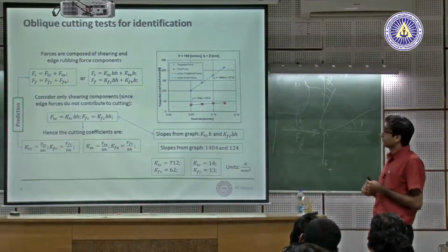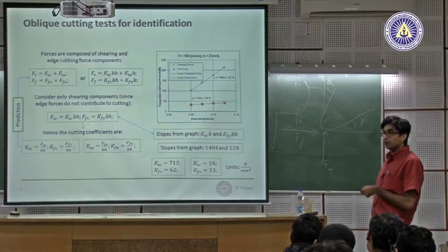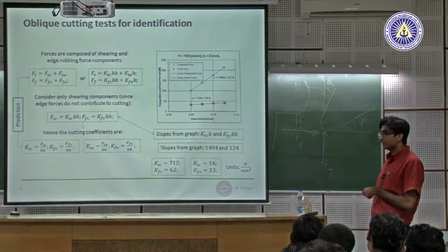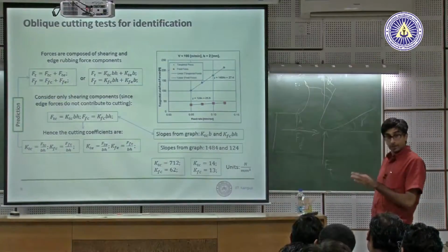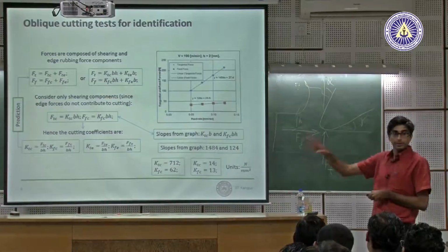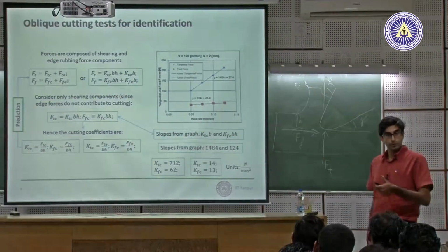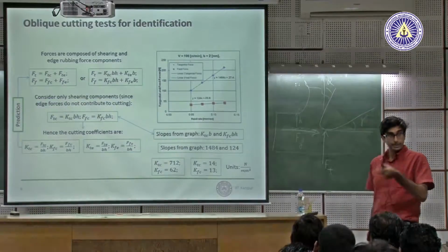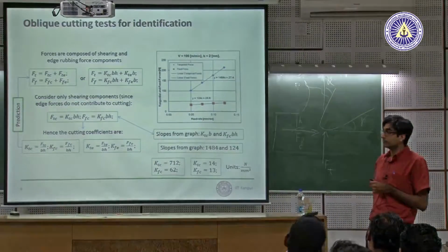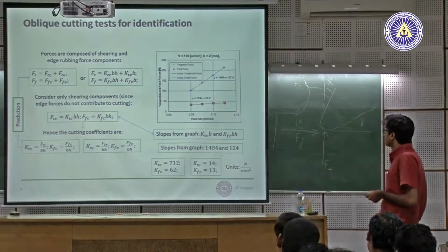Then you will know that these make sense. Once you validate them with another set of parameters, you can store them in your database and use them for force prediction, torque prediction, sizing the motor, sizing the spindle power, or chatter prediction in the later instances.